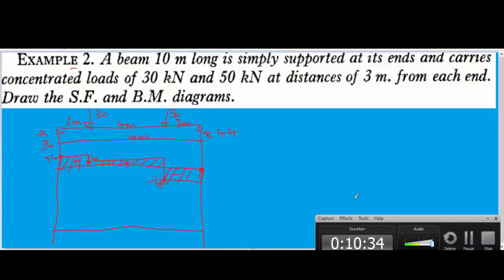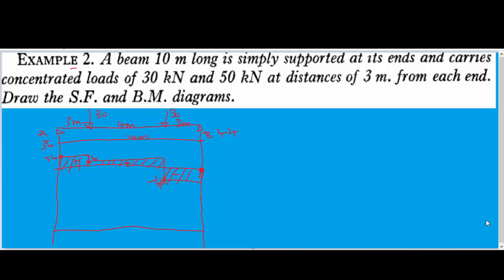So we are back. All we have to do now is to get the bending moments diagram, and to do that we'll use a simple method, which is our area method. As you can see, this particular shape is rectangular in nature. Same thing applicable to here, same thing applicable to here. But in some cases you might observe you have things like triangle, trapezium. If you have trapezium, you can divide into many sections. In our next example we'll touch something like that so that you can understand how this works. You can have a parabola and how to use other methods to solve them.